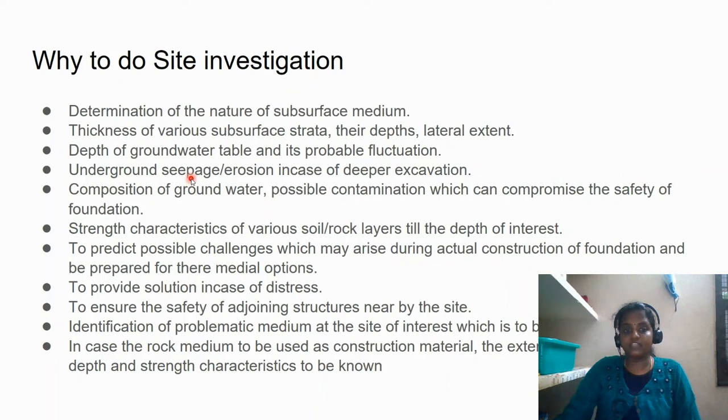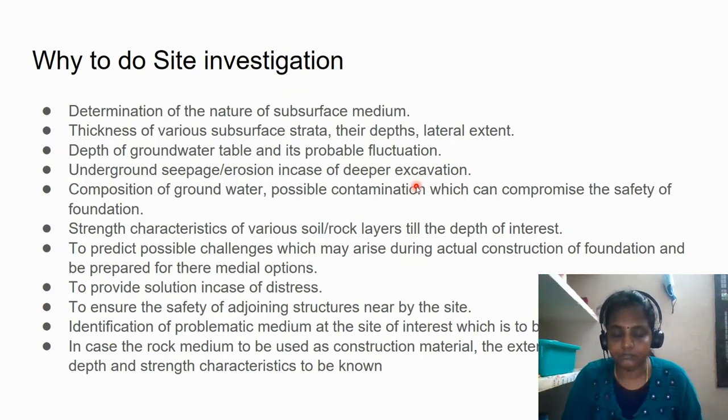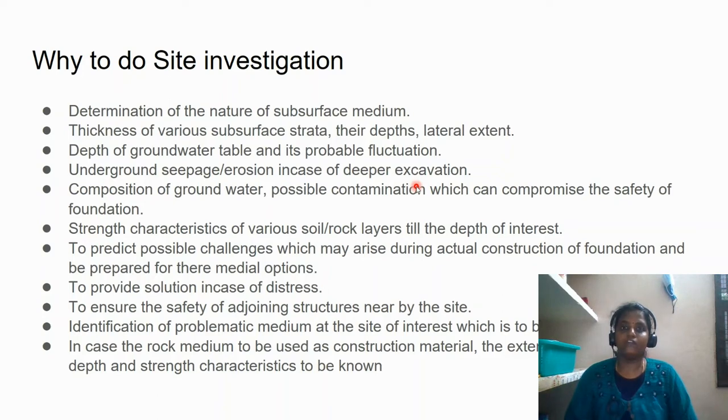Next is underground seepage or erosion. When we do a deeper excavation, even now for skyscrapers like G+20, we go for 3 floors below for parking itself. So when we do a deeper excavation, we have to see if there is going to be any seepage or erosion issues. This also occurs in bridges, especially. There are case studies where, because of continuous erosion, the bridge piers or foundation have been exposed. So we have to see that.